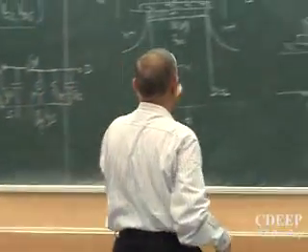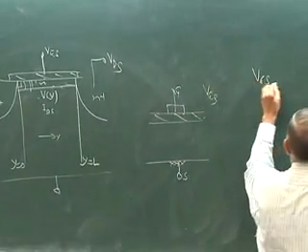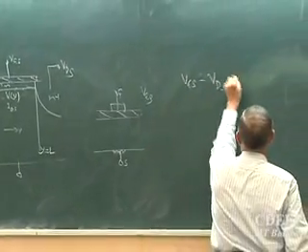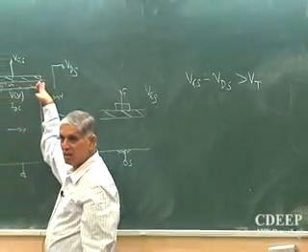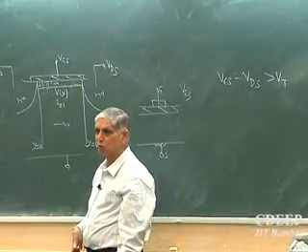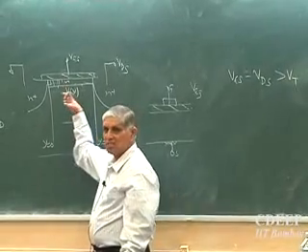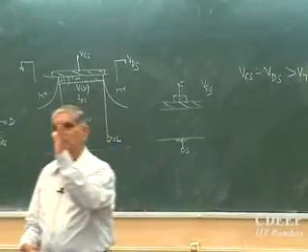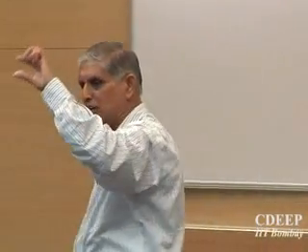So it may happen that as long as this voltage minus this voltage exceeds the threshold voltage, inversion will set in there as well. But in the portion where it does not have that exceeding voltage, inversion may not exist. Is that point clear? So is it different from a capacitor? It is as if there are a number of such capacitors stacked together, and at every point there is a different VGS. Wherever it exceeds Vt, inversion will occur. If it doesn't, no inversion can occur.